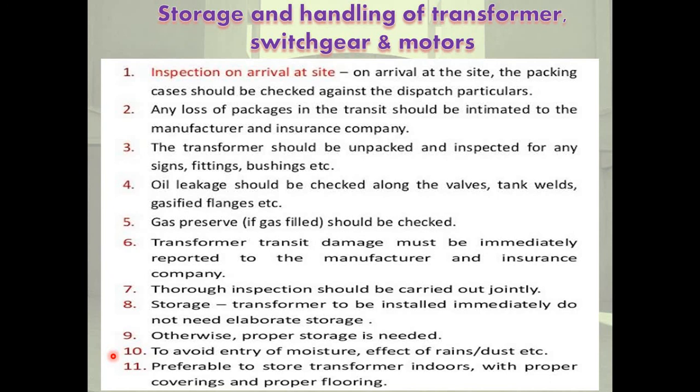The composition of the concrete used for machine foundations is cement 1 part, broken stone 4 parts, sharp sand 2 parts. In bed plates, medium and large rotating machines are installed on bed plates in one piece or sectionalized, or separate for motor and generator. For mounting bed plates on large machines, pads and foundation boards are used in the installation.